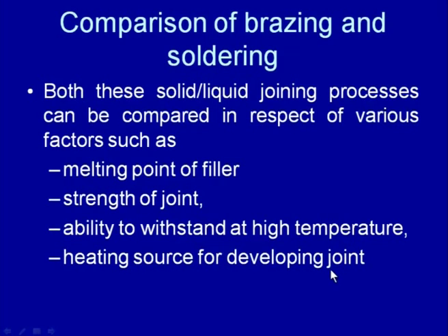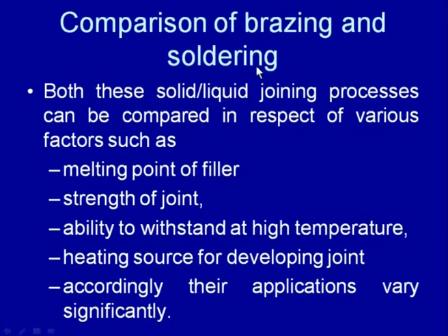There is a slight difference in the heat source which can be used for the two processes, and based on their ability to take up load, the melting point of the filler material and the ability to withstand high temperature, these two processes find applications in different areas. Under conditions where the mechanical load between the components being joined is not much, soldering is very commonly used in the electronic industry, where the connection is required mainly for the flow of current or signals from one side to another through the joint.